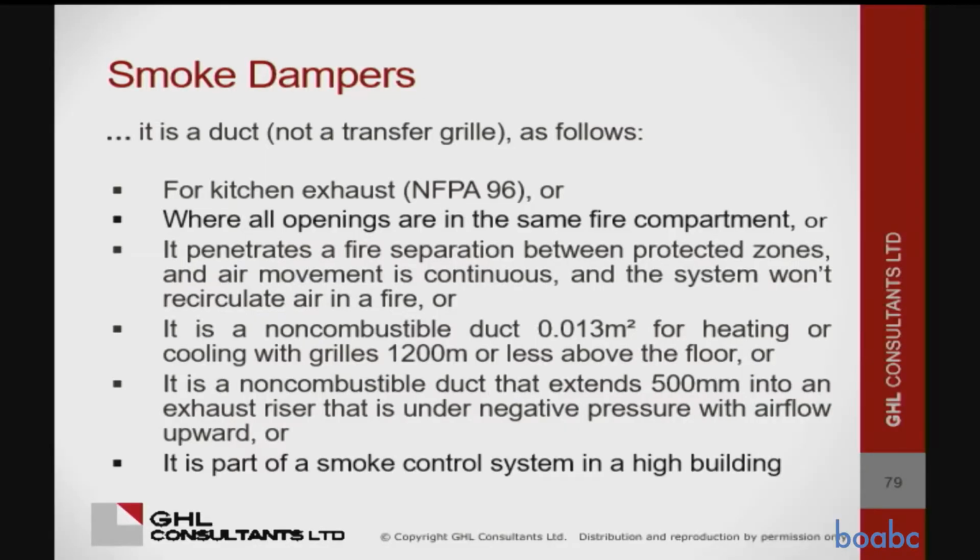So unless it is a duct and not a transfer grill for a kitchen exhaust, where all openings are in the same fire compartment, which, as we talked about before, a fire compartment is defined as being bounded by fire separations that have a fire resistance rating. So basically what that's saying is if all the openings are in the same fire compartment and your duct is passing through an unrated fire separation, then you don't need a smoke damper.